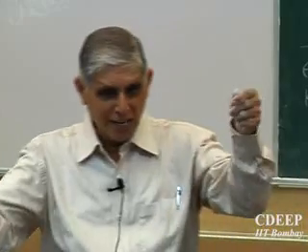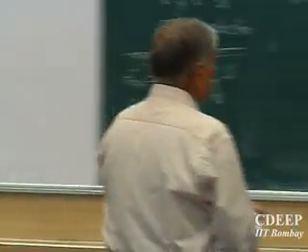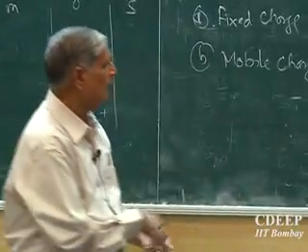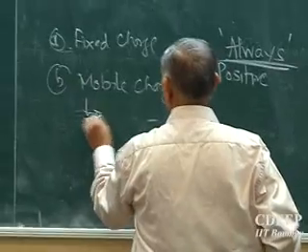In a MOS transistor both will occur. You will apply electric field and the device will get heated because of current flowing, I square R will be there. So the mobile ions will move during operation of transistors. Now the problem with the other charge is, so mobile charge is essentially sodium related.